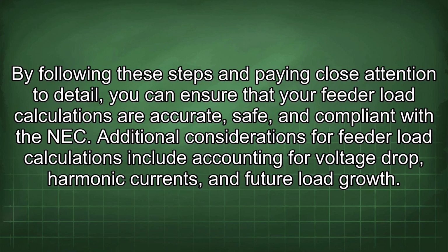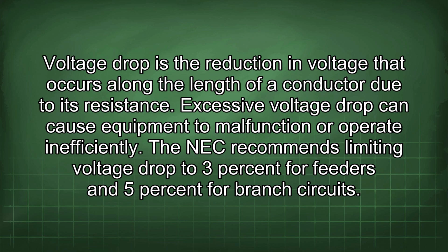Additional considerations for feeder load calculations include accounting for voltage drop, harmonic currents, and future load growth. Voltage drop is the reduction in voltage that occurs along the length of a conductor due to its resistance.